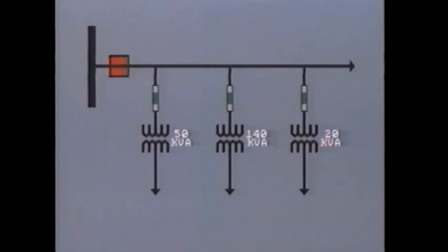On smaller transformers, it is usual to omit the primary side breaker for economic reasons. Typically, we may have many large and small distribution transformers tapping off a distribution feeder. The feeder will be fed from the substation bus through a breaker, but each distribution transformer will be protected by high voltage fuses only.